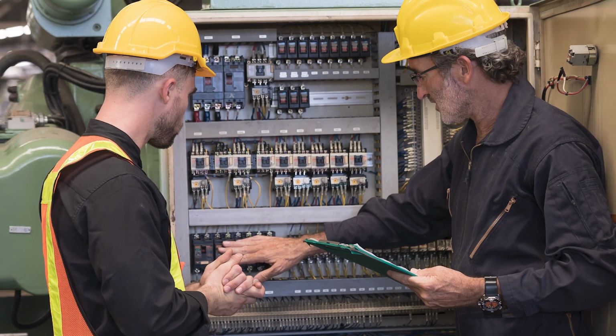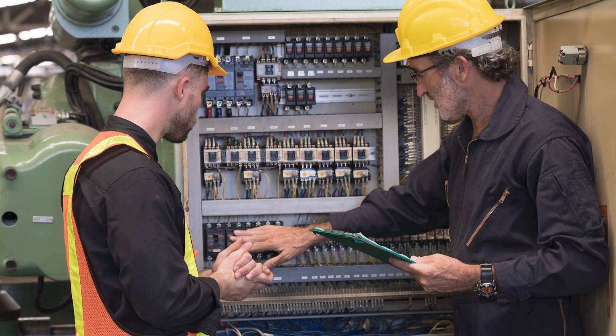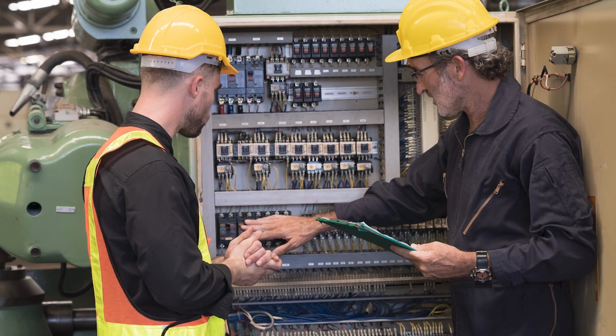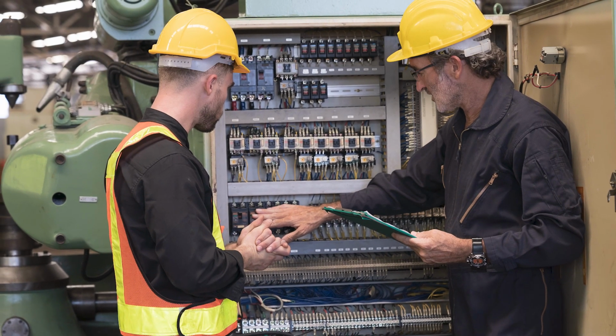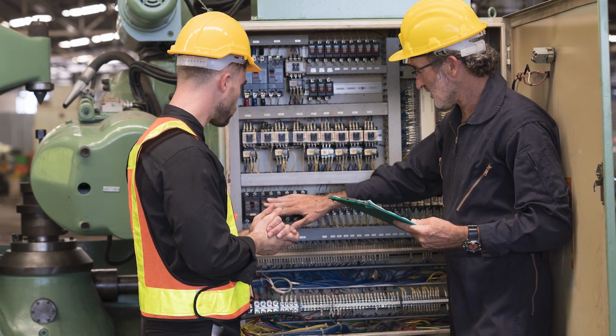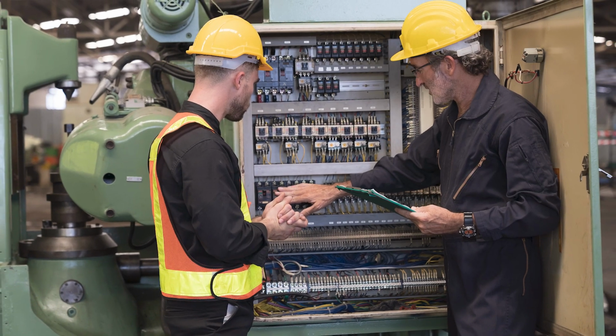If nothing changed in your facility, it might be as simple as let's talk to the utility and make sure the fault current values haven't changed, and just have a site visit to ensure that, yeah, it's still a valid calculation. But anytime you have the utility making changes, or you make changes inside your system, 70E is going to require your arc flash study to be updated, but it is a 5-year maximum review of that study.